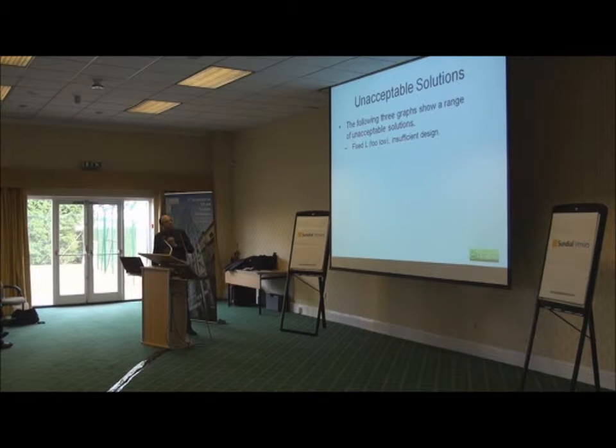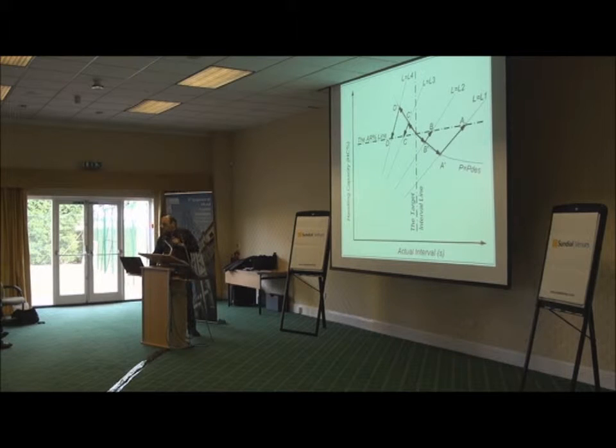You are either forced to have too few lifts by the architect. So the architect says you can only have 3 lifts and you need 4. We'll see where that is. That's an insufficient design. Too high, for some reason you had too many lifts. It's the wasteful design. You started with too many passengers. That's a wasteful design. Or you started with too few passengers.